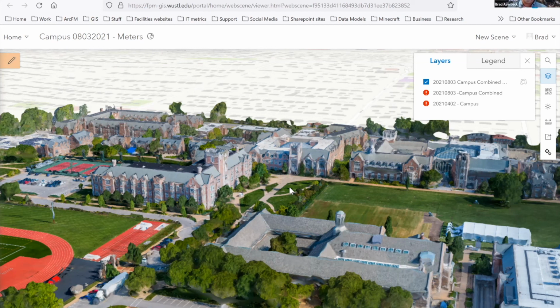But it's really about, even with drawing in the map version, right? I tell people don't do complex objects. You can draw a nice little box around it and then come back in ArcMap and actually add detail to it, because you don't get the snapping and you don't get the fine control of drawing within the online map.